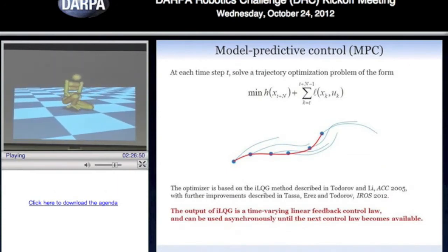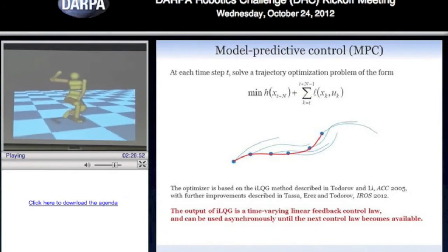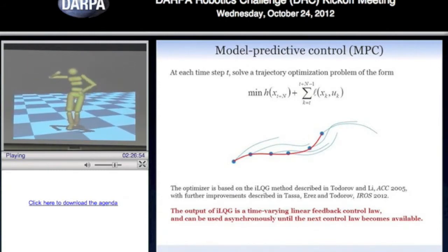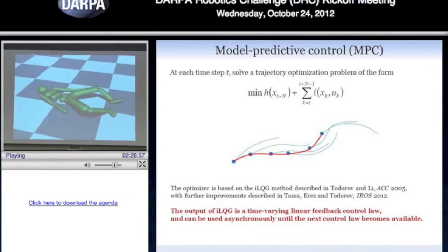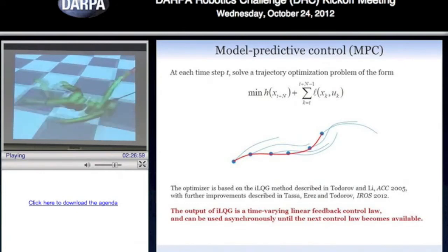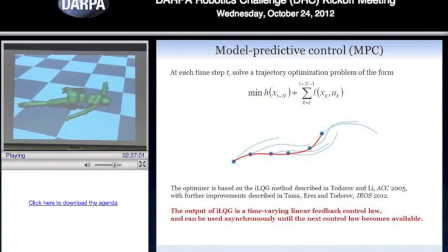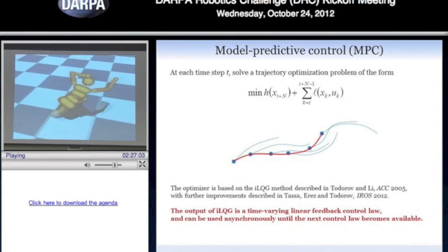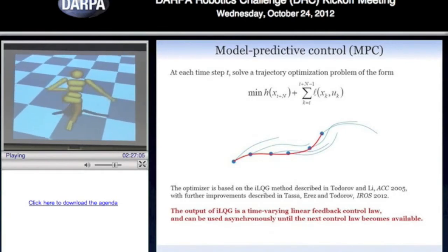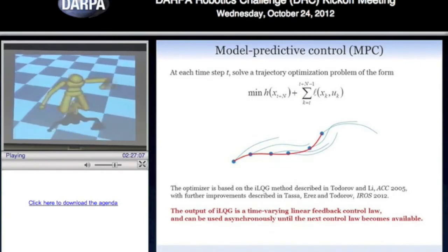Okay. Same idea applied to a full humanoid. The task is to get up. So the cost function just says, put your torso 1 meter over your feet. We don't care how you do it. This is passive dynamics. The red things are external forces we put into the simulator so we can drag it around. When it's orange, it means that we enable the controller and it invents how to get up.